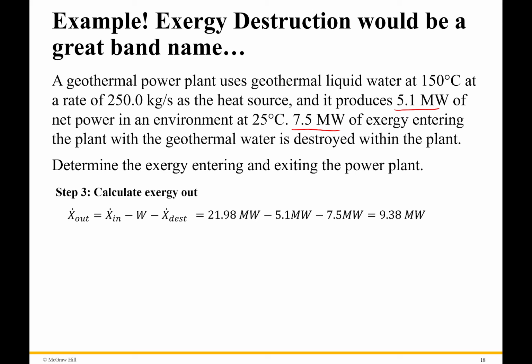So with this, hopefully you can see that we're dealing with Exergy. It's not all that scary of an equation. You just need to know the entropies and the enthalpies usually, and you can solve for the Exergy. Beyond that, just know that it's note keeping. Just like this, you're going to have Exergy. It can't just magically disappear. It has to either be destroyed, or it's exiting, or it went into work. As a note, when we say Exergy destruction, we're talking about Exergy that did not do anything useful. We didn't produce any power with it. It just got wasted.